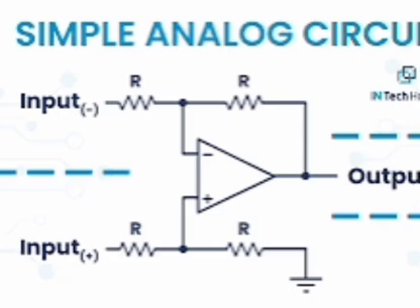Common base configuration: IE equal to IB plus IC plus ICB0, or IE equal to IB plus IC. IE means emitter current, IB means base current, IC means collector current, ICB0 means collector to base leakage current. IB equal to 2% of IE, IC equal to 98% of IE.